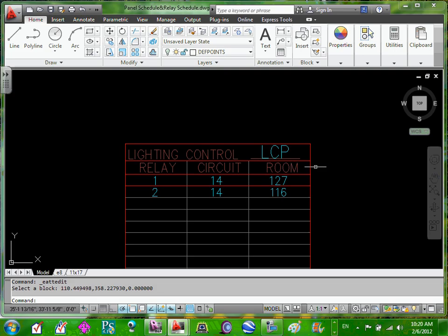I don't know if you want to edit this one and add the side control type, but it's also clear if you go to the room, it tells you whether it's an occupancy sensor or circuit or whatever. But this is easy because there's no place in the drawing that tells me which relay is controlling what. So this will give you an identification of all the relays. Room 27 must have something to control that relay. It could be an occupancy sensor, a low voltage switch, or a high voltage switch. We're switching it to sweep the area. Can I have thumbs up, guys?